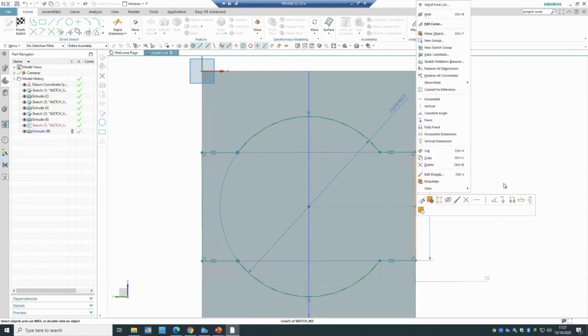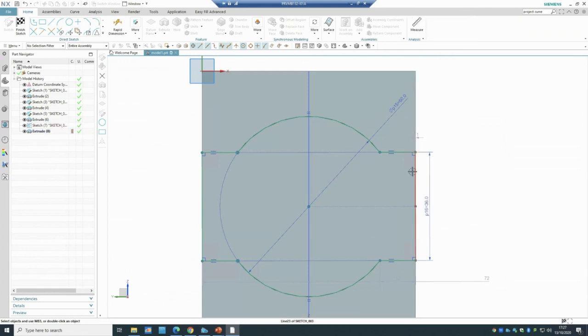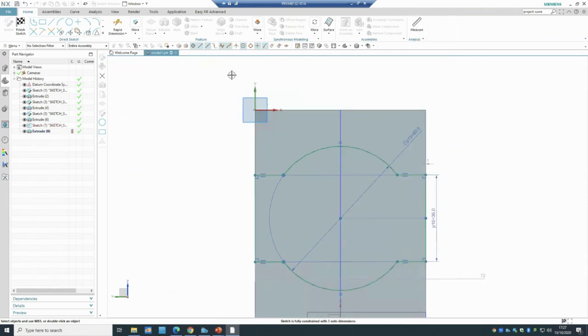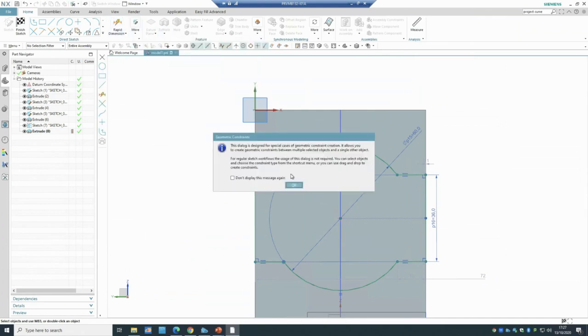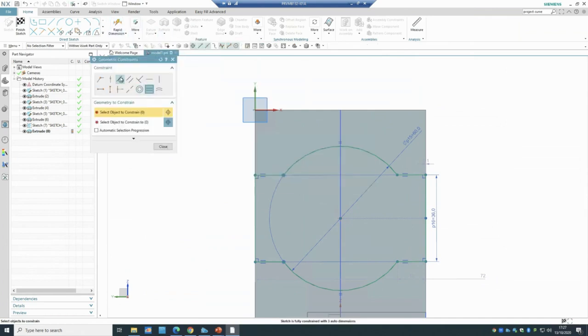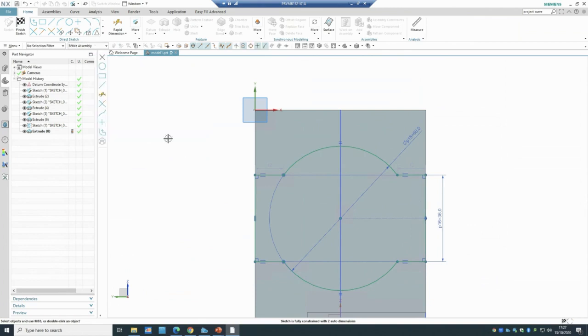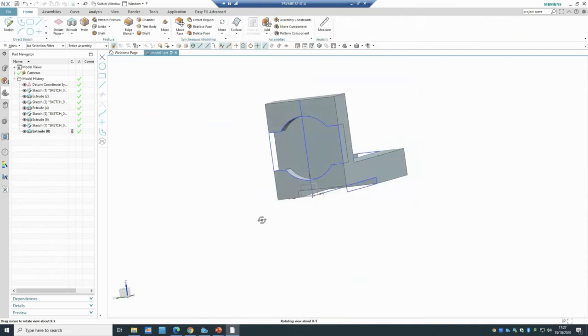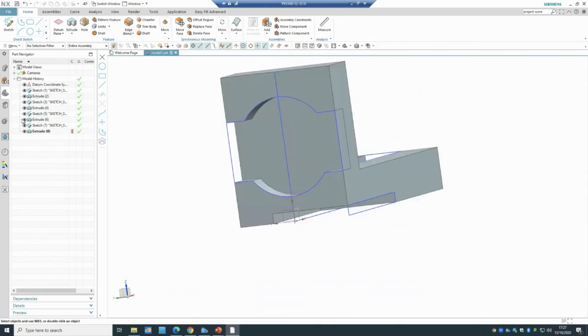Okay, do you see what can be the issue? It can be about these lines that they are not vertical. They have to be because they're perpendicular. Let me double check. It happened to me in the morning that the solver was showing me the error, but then it's okay. Let's see whether everything's fine. Vertical, vertical. Okay. The solver didn't realize that these two lines are vertical, so I've made them vertical, and this one is correct. Still, this one shows me an error. I will come back to it.